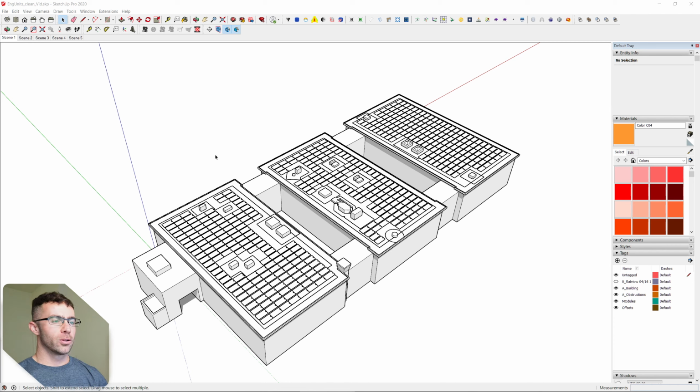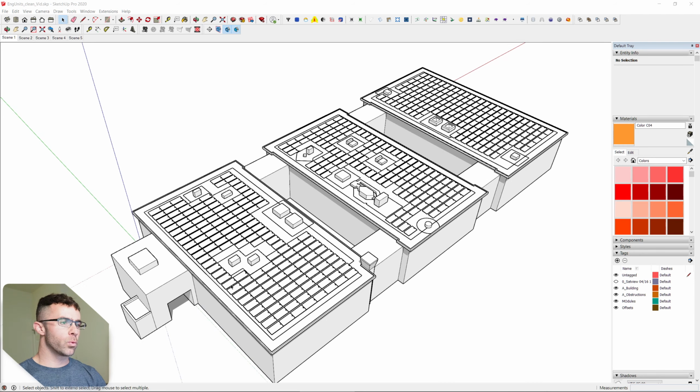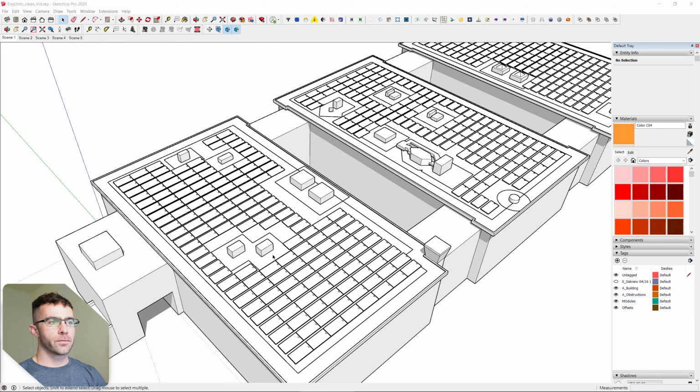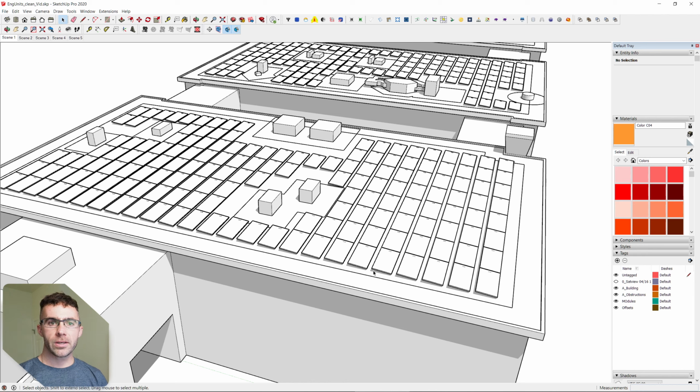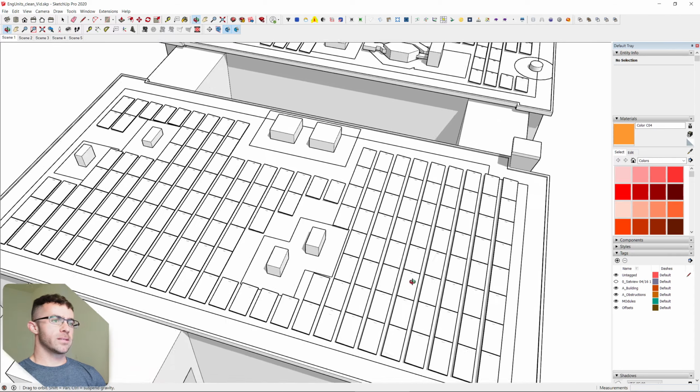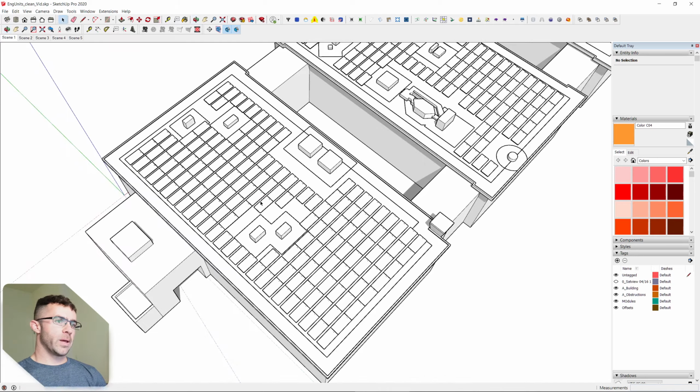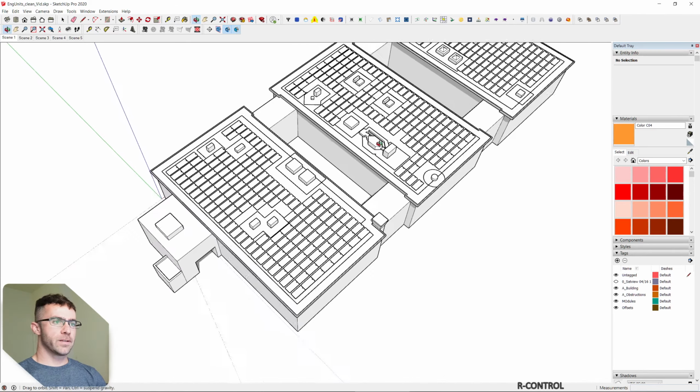So we looked at how many modules we could fit based on physical constraints. We took care of the offset for access around the perimeter. We also looked at setbacks from equipment for working clearances, as well as roof access hatches. And then we also looked at inner row shading. We were using the 10-degree racking system for our first iteration, if you will. And this established the number of panels that we can fit on the roof given the physical constraints.